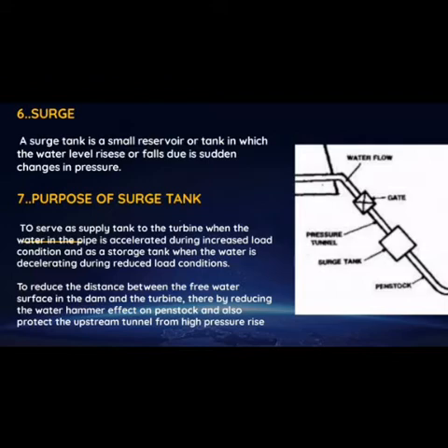So next, six, surge tank. A surge tank is a small reservoir in which the water level rises or falls due to sudden change of pressure. And seven, purpose of the surge tank: to serve as a supply tank to the turbine when the water in the pipe is accelerated during increased load conditions, and as a storage tank when the water is decelerating during